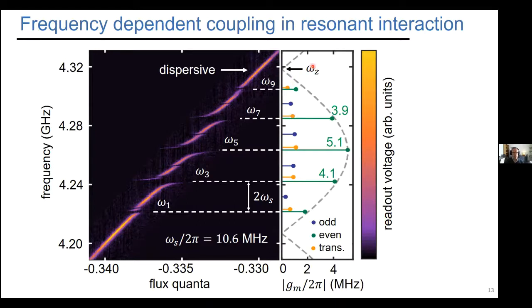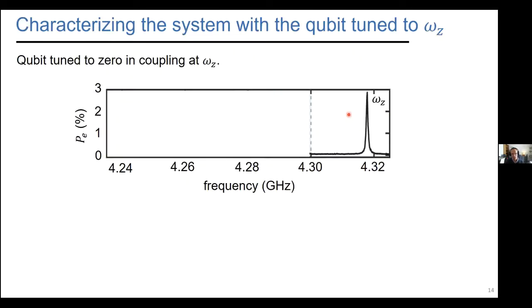So to see if you've achieved the strong dispersive regime, where we can resolve the dispersive shift of a single phonon, we tune our qubit to this frequency. At this frequency, we can do spectroscopy. We can see its line width is a couple hundred kilohertz, and this isn't so great. But what we've made is a really fine pitch capacitor. They're 90 nanometer lines, as well as a bunch of things on a piezo. So we're happy, we're proud of this line width, even though it's not competitive.